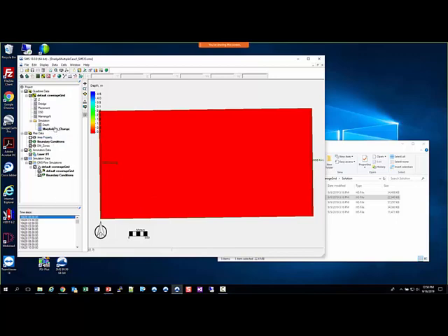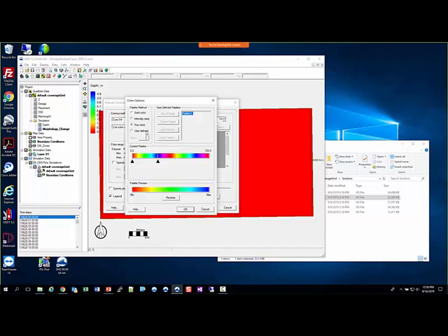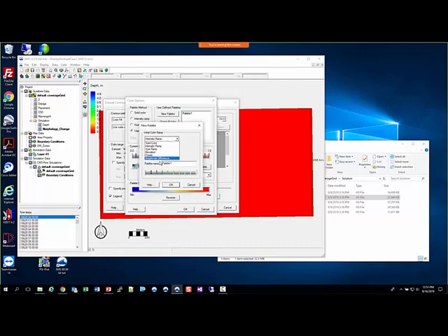And so what I can do is, let's change the colors of this morphology change. I'll right click and change the data contour options. I'll make it color fill. Basically I want to choose a magnitude difference color ramp, and that's what this is.